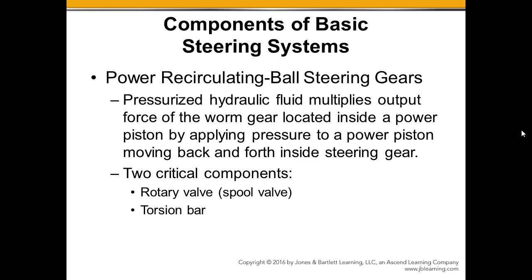For the power assist, we are using hydraulic fluid pressure, the principles of hydraulics, to have a pressurized fluid working on one side of that power piston or the other side to assist us with a right hand or left hand turn, and then able to vary the pressure there to give us more power assist or less. All of that happens within the steering gear.